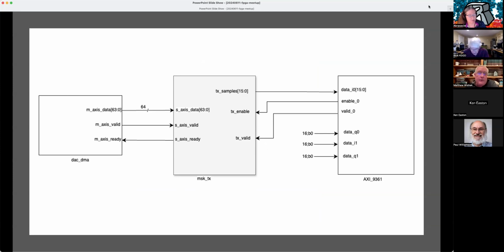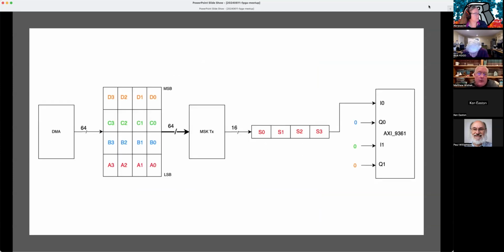You can go to the previous slide. So what we're doing now, we see the A0, A1, A2, A3. It's configurable in a register to say how many bits, but it's just going to take the LSB up to the number of bits. So this could be packed as A0 through that whole column instead of the B0, C0, D0. But right now, in my simulations, I'm configuring the A0 to 8 bits. So even though I'm getting 64 in, I'm just taking the low 8 bits, and then